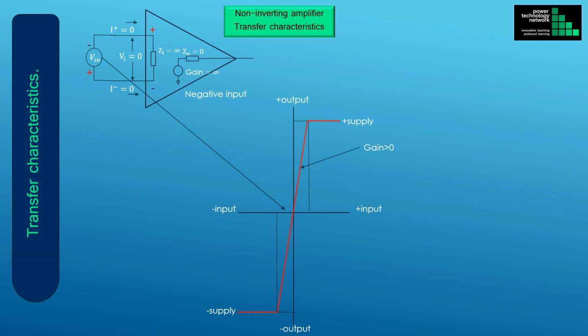Using the model from a previous slide, and with a negative input voltage, meaning that the negative terminal of the input voltage source is connected to the positive input of the amplifier, the operation is in the third quadrant. The amplifier gain is positive, because the positive terminal of the amplifier is used as the input terminal, and the input voltage is negative, therefore the output is negative. The input voltage varies in the negative range shown here. The output is clipped to the negative rail voltage.